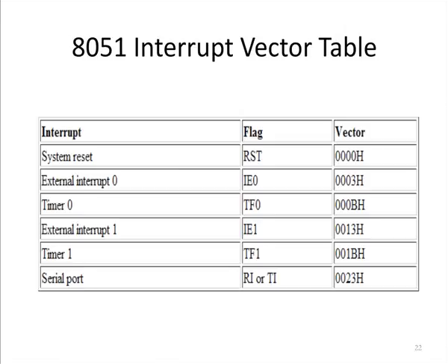We have seen the block diagram of 8051. We have seen that the 8051 has 4 different ports, namely P0, P1, P2 and P3. All these ports are 8-bit ports and each port has 8 dedicated lines which can be programmed either as the input or as the output.